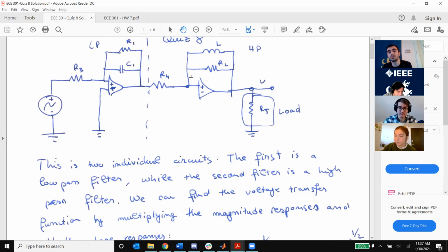So this is also not going to allow the high frequencies. So this is going to give us what is called a band-pass filter, which allows only a band of frequencies. And it is very useful. The way to study these things is transfer functions and Bode plots. So we will explain with MATLAB how to get these Bode plots.